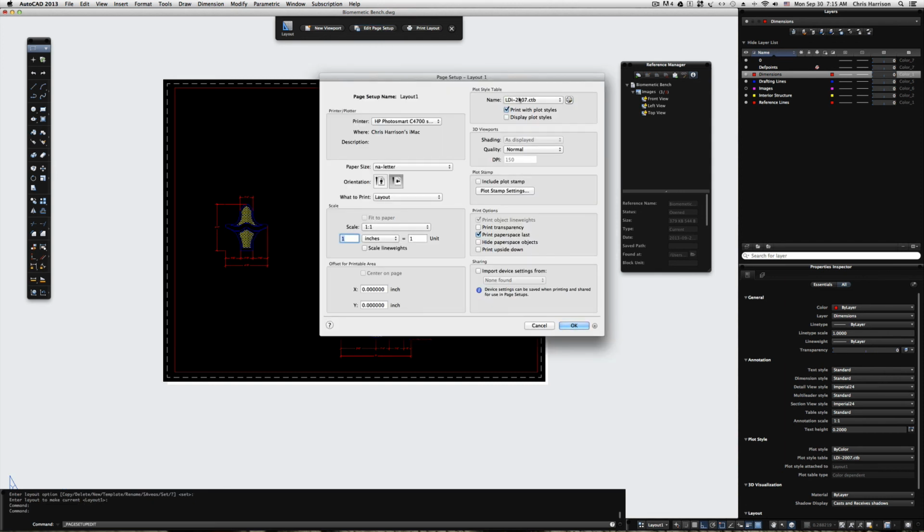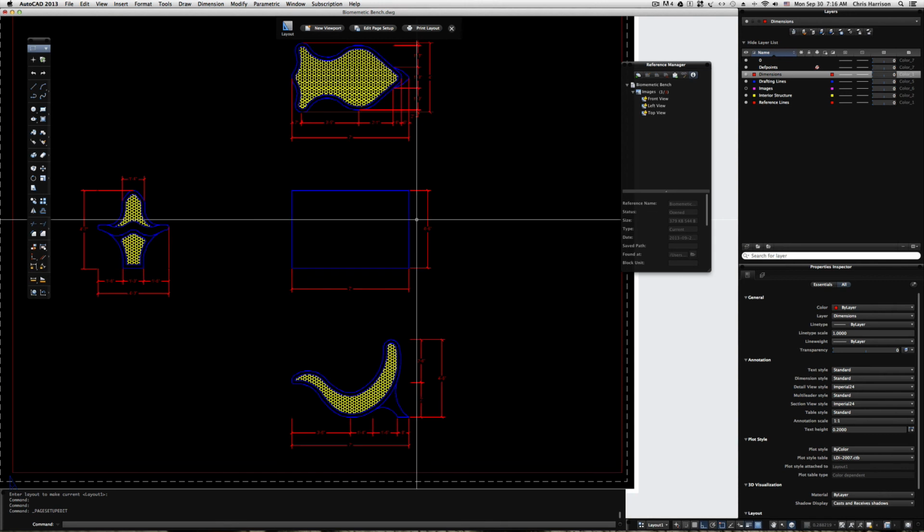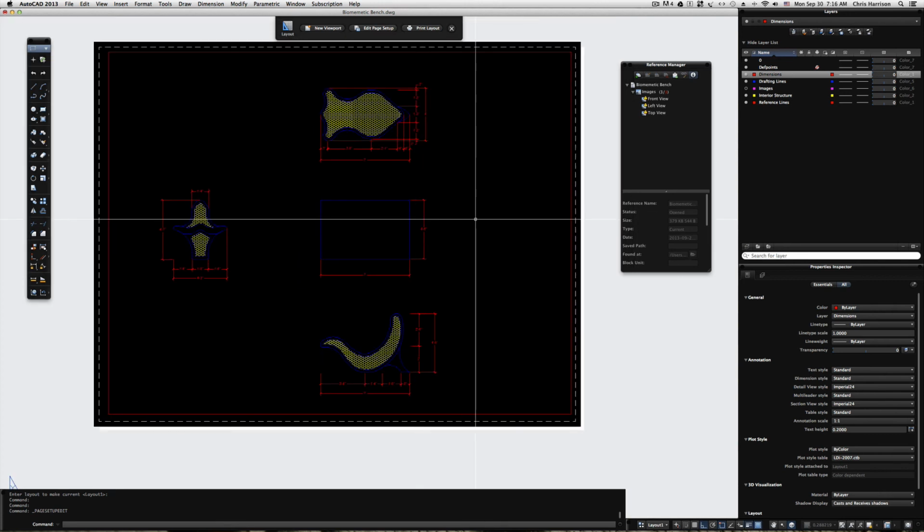I'm just going to click on this on mine. You'll see that we have pen settings. I'm using LDI, which came from a firm that I work for. Same principle, but the colors are a little bit different. Let me explain that. The way that works is that when we draw, and this is something you're all familiar with, we talked about using line thickness. Well, in CAD, since everything is drawn basically on one plane, you don't really specify line thickness because you're using a mouse as an interface. You are able to allocate a color to a specific size, a width.